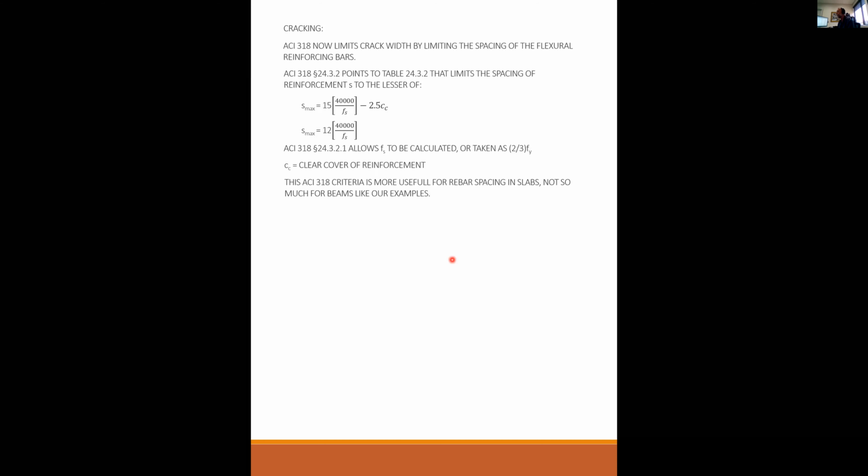At some point, you need to choose how deep the beam's going to be, not D, but H, the depth of the beam. And what you choose is what you're going to ask the contractor to build. So you better make it an even module, 28, 30, 32, 34, 36, something like that. And once you choose the depth of the beam, then you calculate what D is based on your choice.